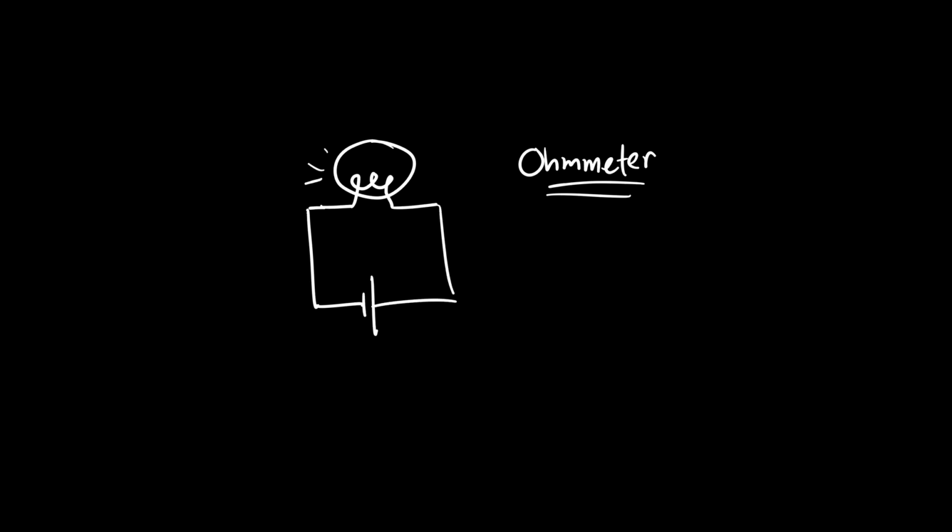And that is because once the bulb is connected and lights up, it gets hot. And once something gets hot, its resistance changes. Most objects change their resistance depending on their temperature. So Ohm's law really only works for a narrow range of A, devices, and B, temperatures. Now, resistance is measured in ohms. And the symbol for an ohm is the Greek letter omega, just a little horseshoe. The unit of the ohm is volt per amp.